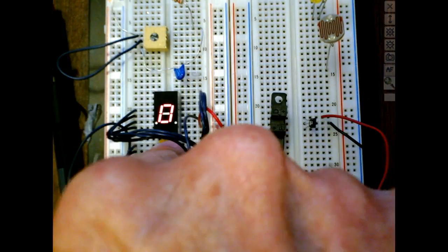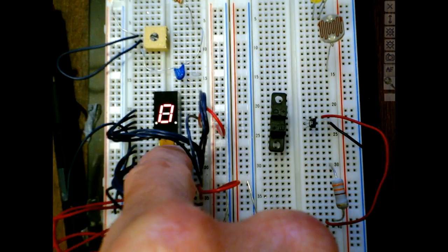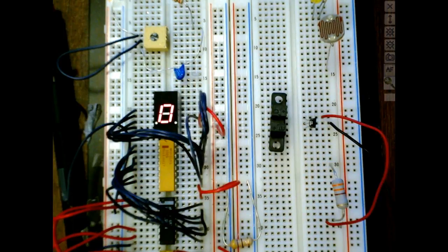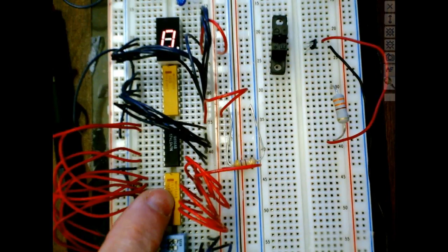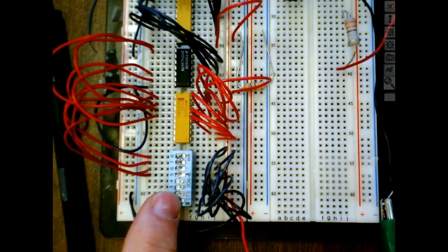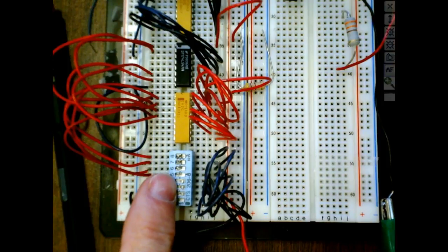When we have to use an actual resistor, which we have to do here, because these are not pull up and these are not pull down resistors, these are strictly resistors, then we would use the DIP. This is a 7447. Then I got another 1K. This is a 1K resistor pack. Here's my switches that we're going to be using. Yeah, so I'm not using the trainer. I'm actually wiring the circuit up, just like it is on the diagram.